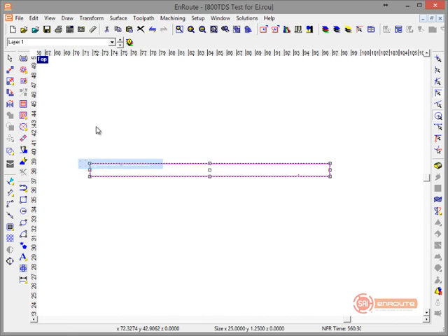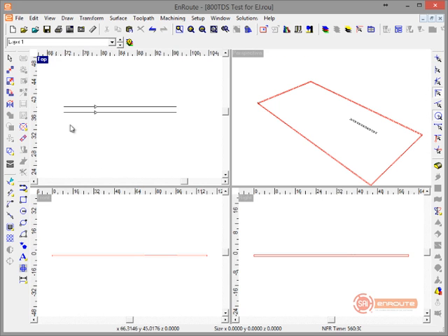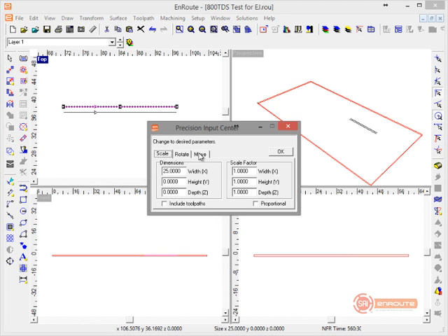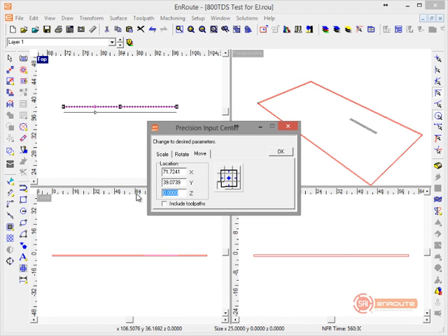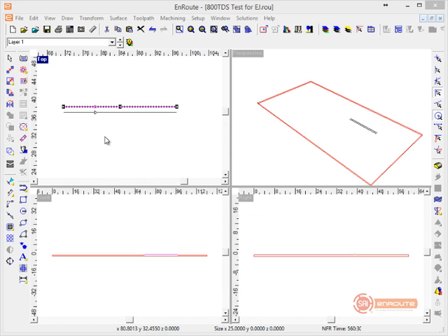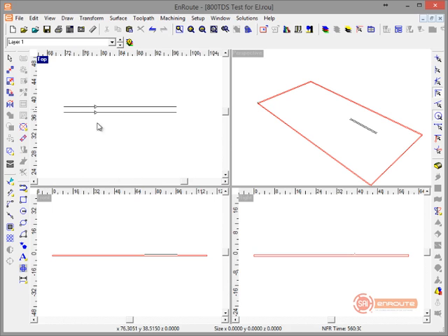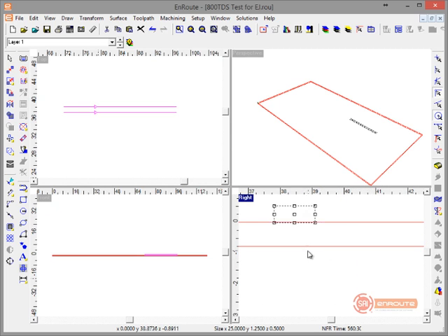I'm going to explode this part and get rid of the corners. And I'm going to have both the rails go in the same direction. So I hit reverse, open contour now. They're both going this way. Now I want this to be ramping down into the part. So I'm going to take this piece and I'm going to move it from 0 to 0.5. All right, and now that will create my difference in height that I'm going to use to be able to